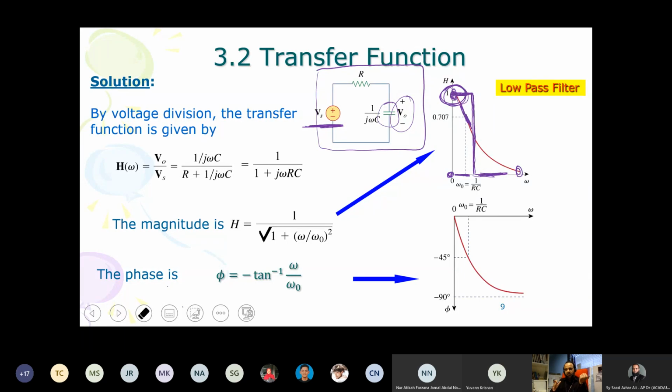If you forget, you can consider that for low frequencies, the capacitor is sort of an open circuit and it is maintaining the voltage, whatever the input is. This is coming from circuit theory. For a zero frequency DC, it reflects the same voltage as the source, right?